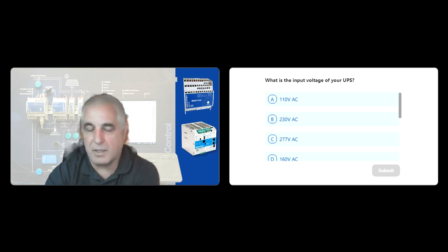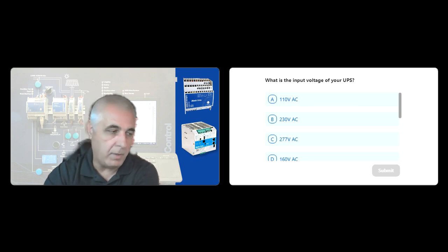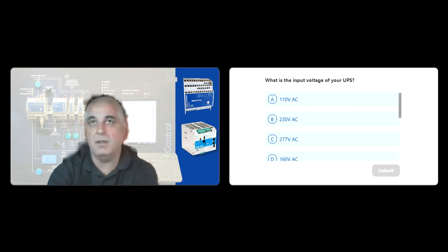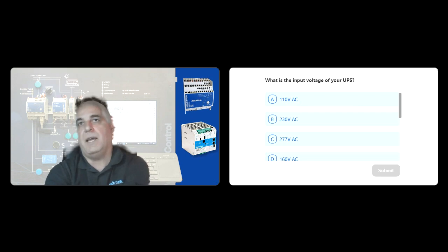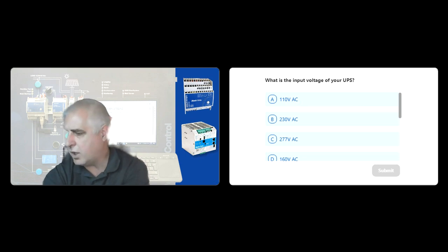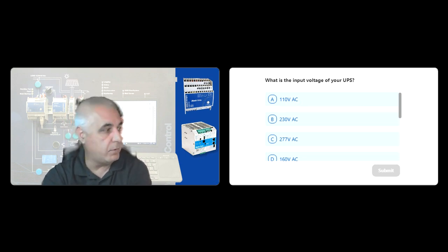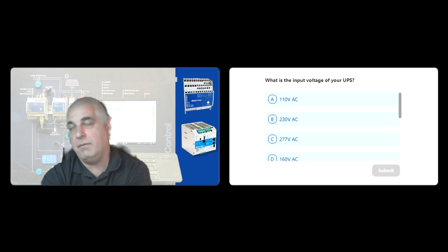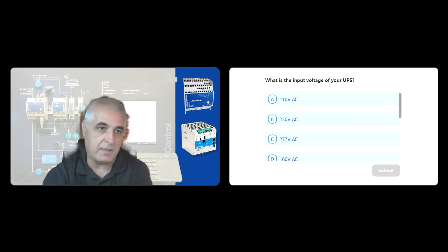Some of our customers obviously combine our system with a solar charger. We have many customers using a DC fuse, basically to protect the system, which is critical. And we have DC fuses that can be set to reset automatically or can be reset manually.